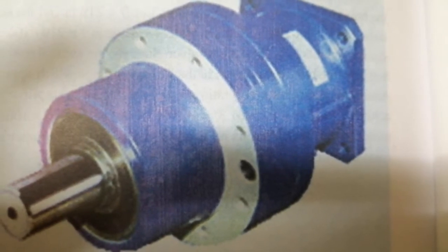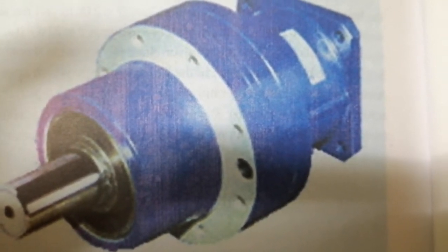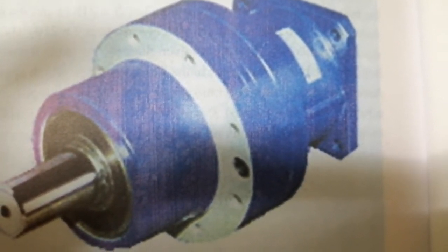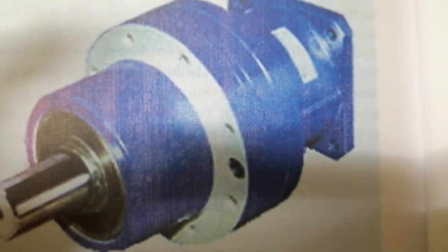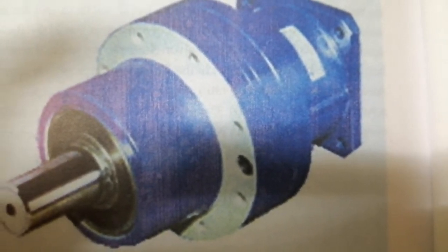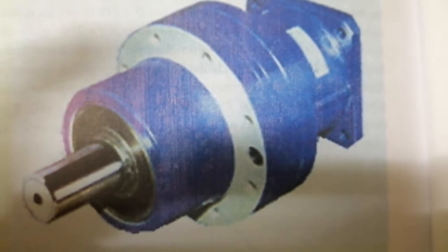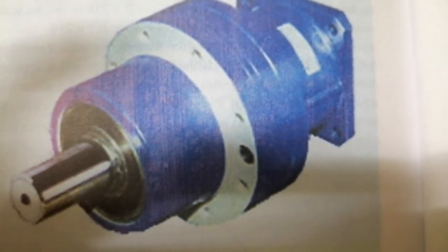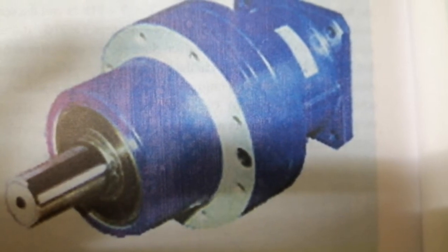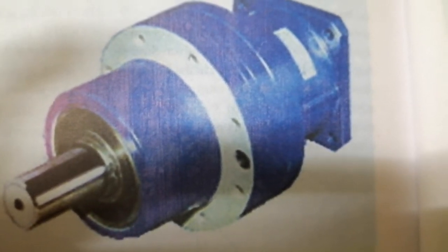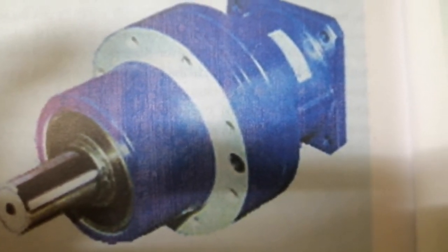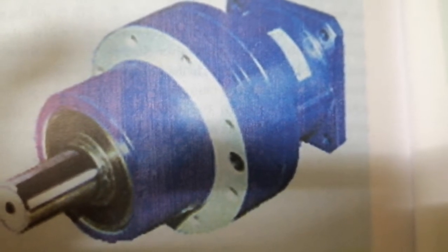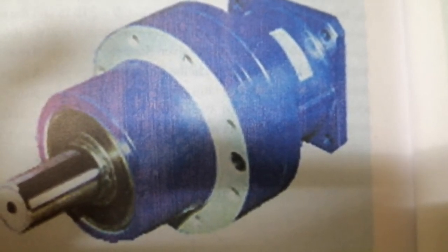They are capable of handling a static position, that is a no motion position, and they do not overheat at standstill or lower speed. As we studied, at no load or at a lower speed a motor overheats, but the main capability of this motor is that it does not overheat at standstill or lower speed.